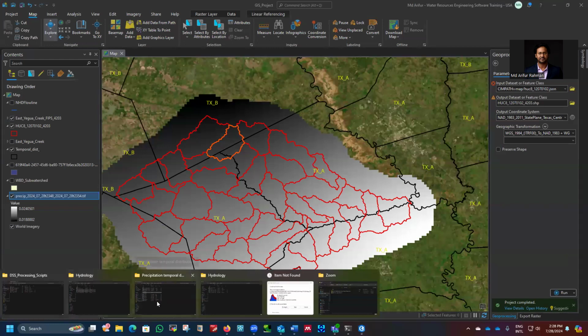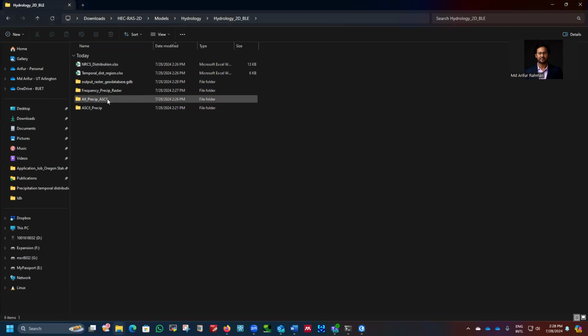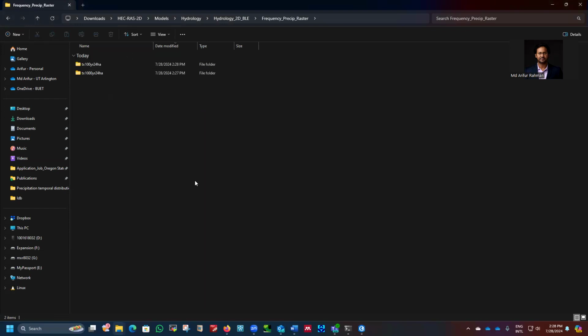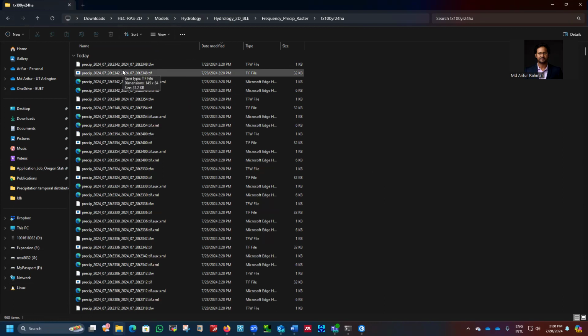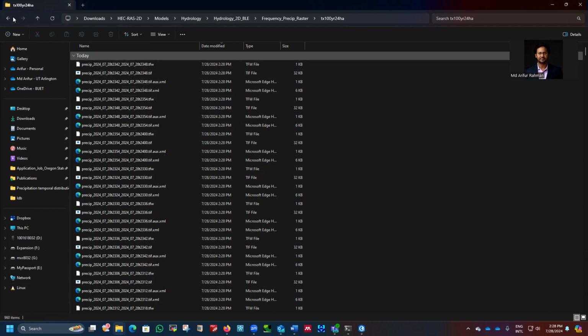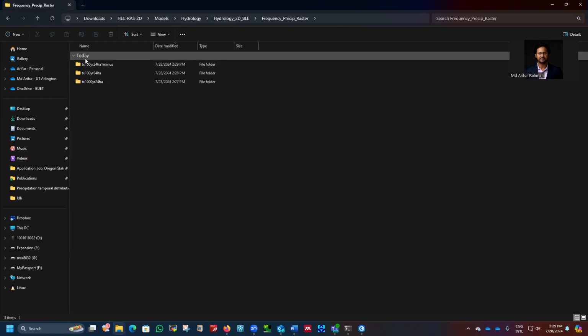Then what we'll do, we'll create a .dss file. Inside this one, let me show you, it is still running for 100 here. Yeah, maybe it's almost done, because we have 11 different profiles. So all the rasters are now basically at 6-minute interval. And say this is also done. It started with the 1% profile. So it's doing the same thing.